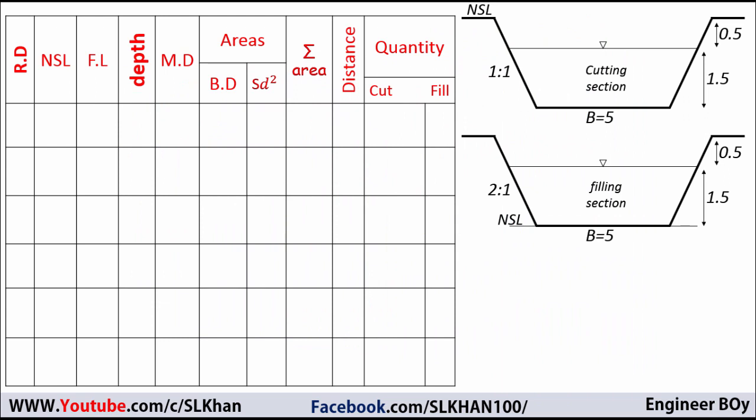So we have here RD, or reduced distance, the NSL, natural surface level, and FL, or formation level, the depth, mean depth, and these are the areas. The summation of area, the distance, and then we'll calculate the cut and fill quantities.